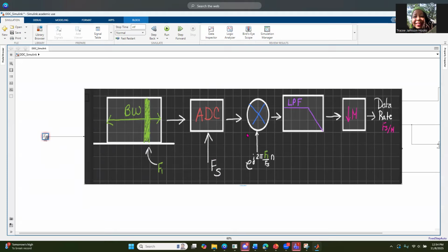And then we are now in the area of our FPGA where we first have a mixer. And if we want to see a select range of frequencies from our incoming frequency, we would then mix our signal with a certain frequency. In order to see that frequency, we would apply a low pass filter because whenever you mix a signal, you will get an image of that signal from the sum products that you may not want. So you low pass filter it.